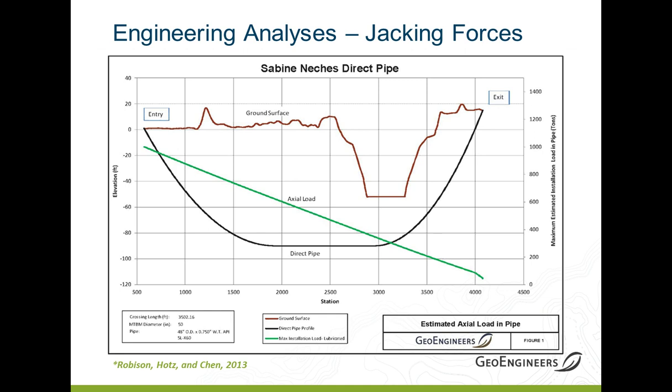And it's important to realize this is a snapshot in time. So this is the load. If you're used to looking at microtunneling data and the load incrementally increases as the crossing is installed and goes up to the right, that's not what this is. This is a snapshot in time at the maximum theoretical loading in the pipe. So that's what we're trying to capture here